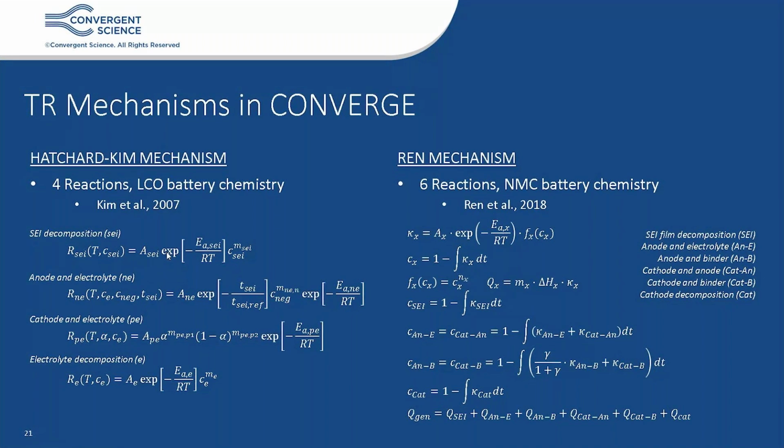So a lot of the expertise we have modeling gas-phase chemistry with the SAGE detailed chemistry solver can easily be applied to model the thermal runaway chemistry accurately. Now, users are free to select between these two mechanisms, and users have the flexibility to change these reaction parameters, like the pre-exponential term and the activation energy and so forth. These reaction rates take into account local conditions, so local temperatures, temperature at each computational cell, and also the species concentration at each computational cell.